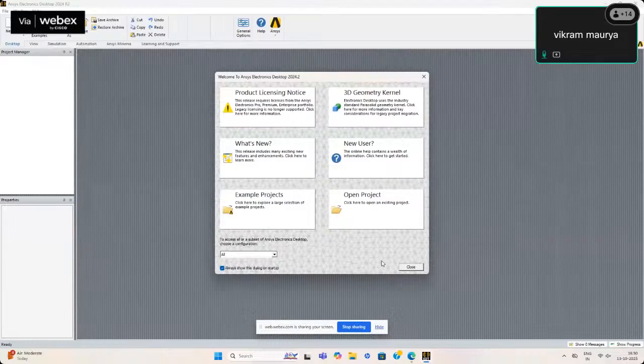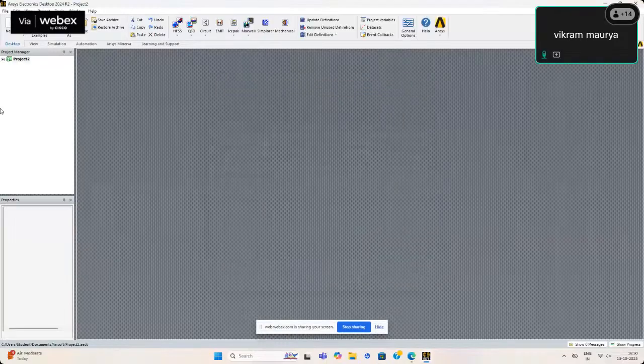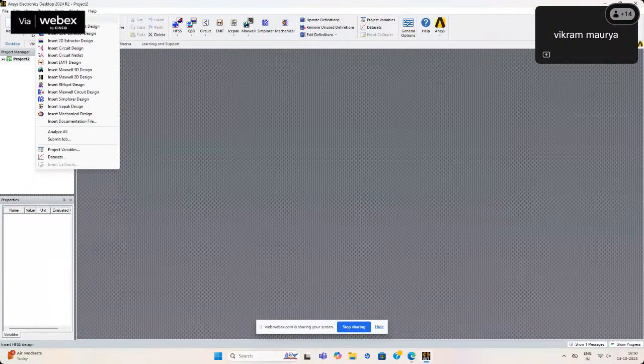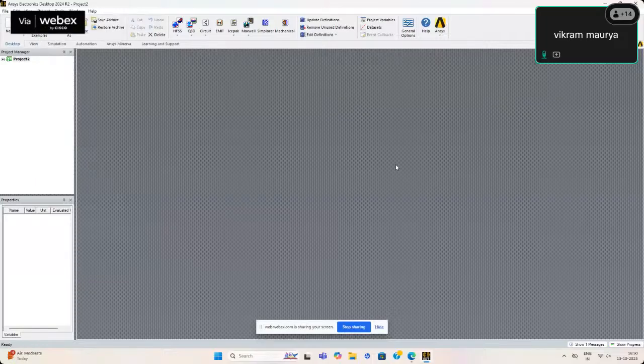After opening this ANSYS software, this screen will come. Go to this project. In project, you have to open insert HFSS design. Just open this. It will take some time, just a minute.